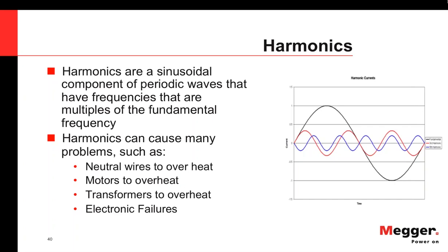Before we get to the RVC, let's go into our harmonics first. Okay, there is a lot of talk about harmonics and where we're going, because as the grid is changing, we are seeing higher frequency levels of harmonics coming out. In the past, we were really looking at harmonics about the 15th order and down. Nowadays, with the higher switching frequencies of inverters, electronics, LCD TVs, we are seeing harmonics roughly from the 35th to the 45th order appearing. Okay?